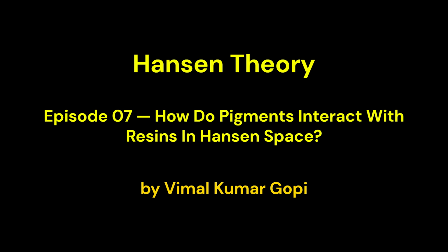Third, hydrogen bonding. Some pigments have active sites capable of hydrogen bonding. Resins or additives with complementary groups improve wetting and stability. Mismatch causes flocculation, clumping, or pigment agglomeration. Now, let's consider particle size. Fine pigments are more sensitive to interaction mismatches than coarse pigments. Smaller particles have higher surface area, amplifying molecular forces. A mismatch that seems minor for a coarse pigment can lead to major defects with a fine pigment. This is why minority-thinking engineers always consider both pigment chemistry and particle size in their calculations.